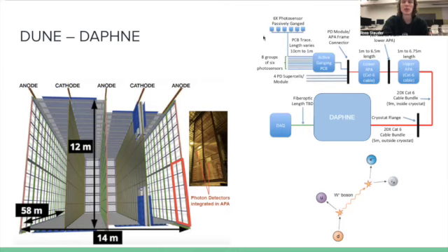You have all these photosensors which are ganged together on the same line, and then you have several hundreds of channels of this which go through the detector through some kind of amplification stages, and they come to this Daphne board, which is the readout board, and it actually does use not necessarily an autoencoder but a feature extraction machine learning algorithm in order to limit the bandwidth, because with this many signals going out, bandwidth is a huge issue for these kind of detectors.